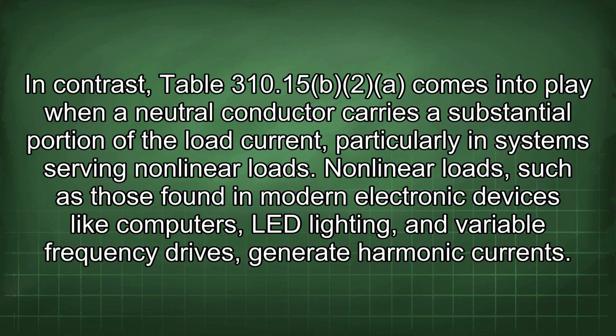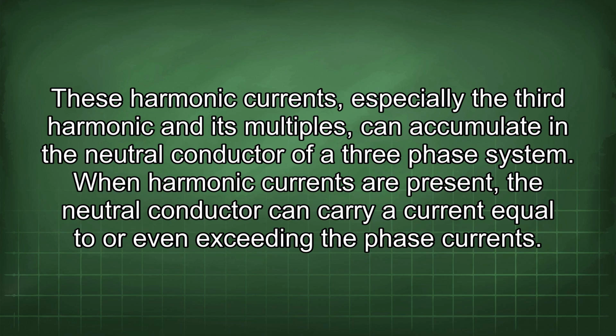Nonlinear loads, such as those found in modern electronic devices like computers, LED lighting, and variable frequency drives, generate harmonic currents. These harmonic currents, especially the third harmonic and its multiples, can accumulate in the neutral conductor of a three-phase system. When harmonic currents are present, the neutral conductor can carry a current equal to or even exceeding the phase currents.